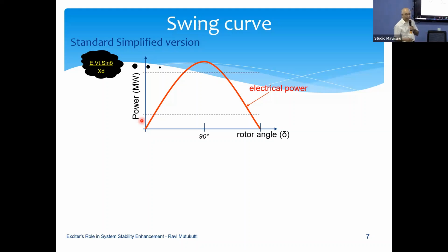This is how you learned this in university or college, by referring to this equation: if you differentiate it and make it 0, then you will get the peak or the valley, right? Because dP/d delta equals 0 gives you either the maximum or minimum. That's how you learned it in school. Now, since I explained in physical terms, you have a better appreciation of this power angle delta, and that operating near 90 degrees is not a good idea.